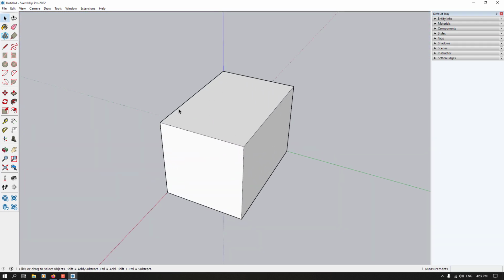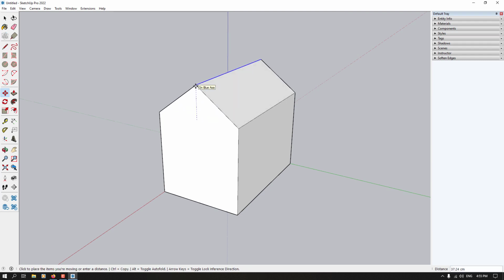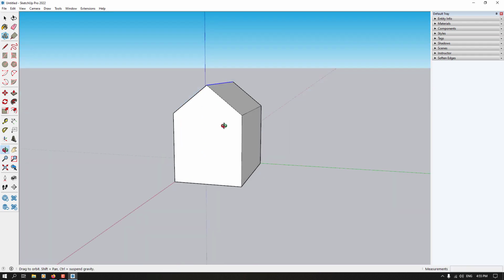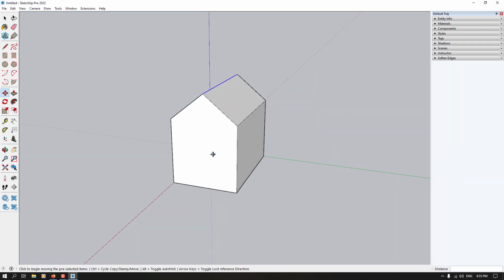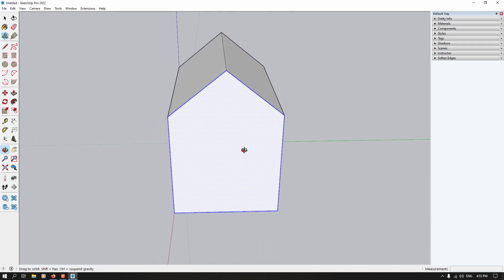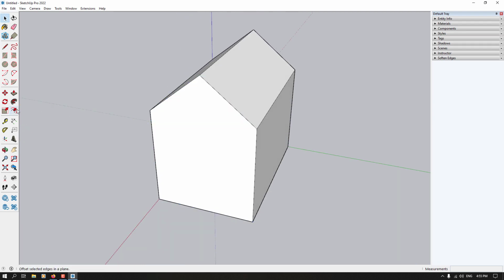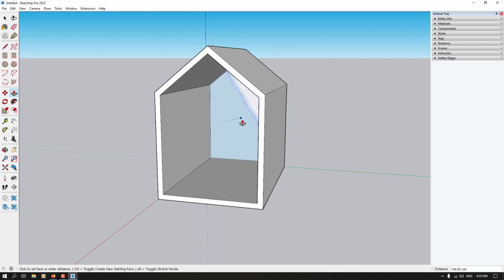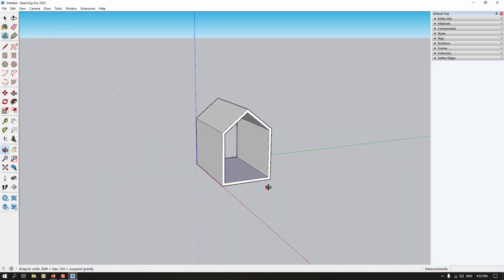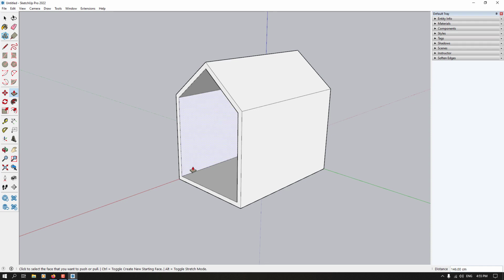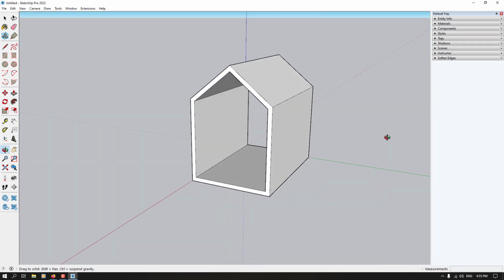Now time for creating the roof. For creating the roof, I'm gonna make a copy of this line in here and move it on the blue axis about 40 centimeter. So now I want to extrude inward on my model faces, so I'm gonna click on the offset option and offset it about 5 centimeter. And now I'm gonna make some interior boolean in it, like 3D Studio Max. We have some boolean option with extrude, very simple and easy.